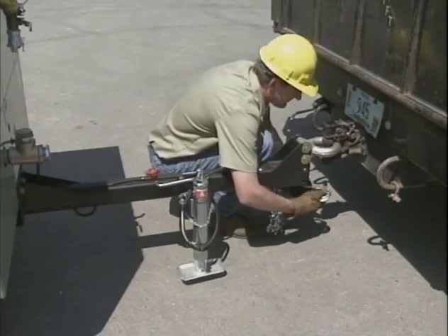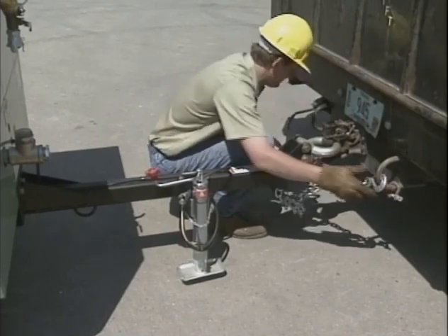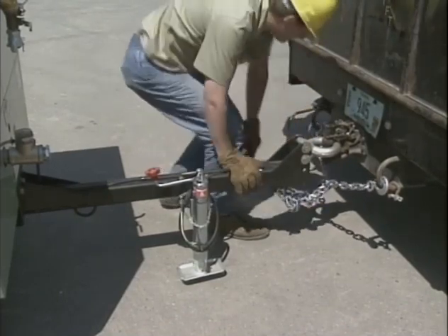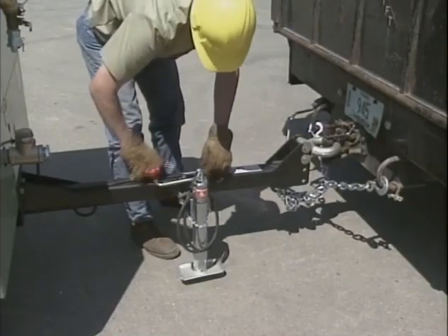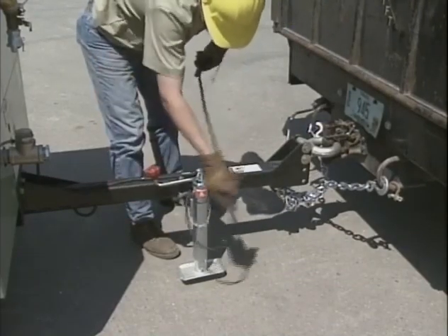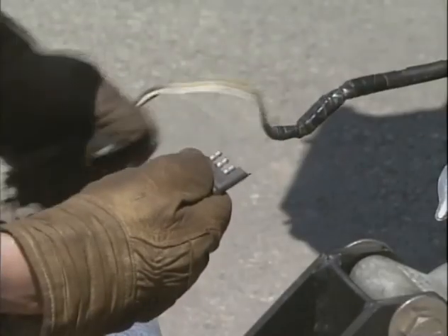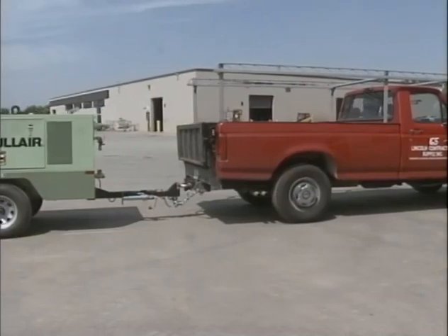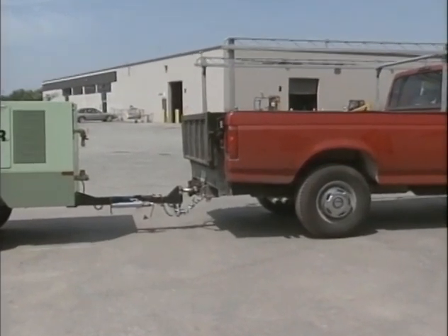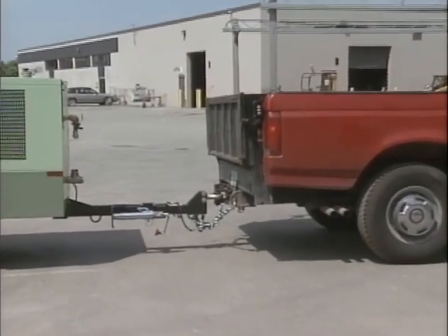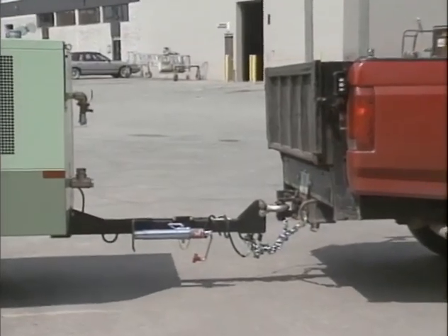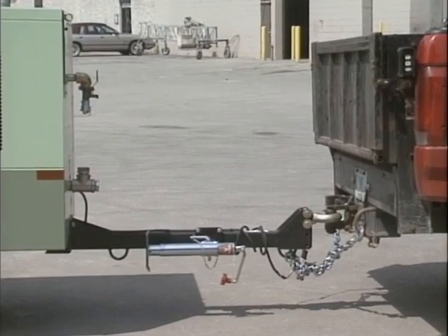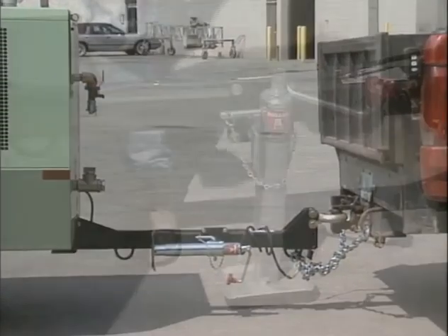Make sure that the coupling device and adjacent structures on the towing vehicle and connections do not interfere with or restrict motion of any part of the air compressor, including its coupling device with respect to the towing vehicle, when maneuvering over any anticipated terrain. If provided, make sure chain length and brake and electrical connections provide sufficient slack to prevent strain when cornering and maneuvering, yet are supported so they cannot drag or rub, which might cause wear that could render them inoperative.